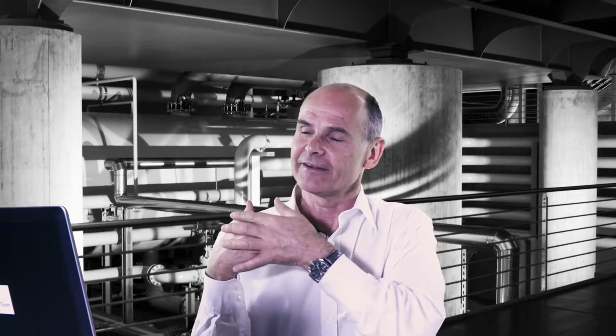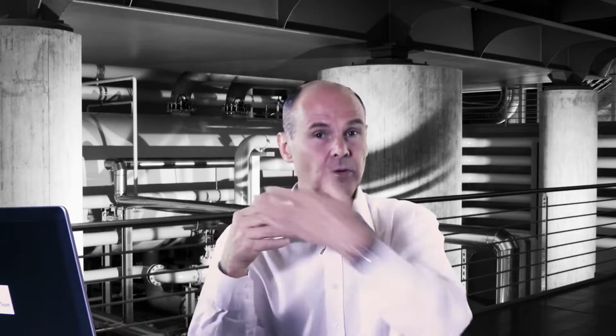And then after the honeycomb we have a number of fly wire screens. You can think of them as basically a fine wire mesh, but in tropical countries you'd use them as a screen to prevent insects coming in. I grew up in Australia, so it's a fly wire screen to me. These screens take any remaining large areas of turbulence. It's becoming smaller because it's passed through the honeycomb. They take that and they break it up into even smaller turbulence.